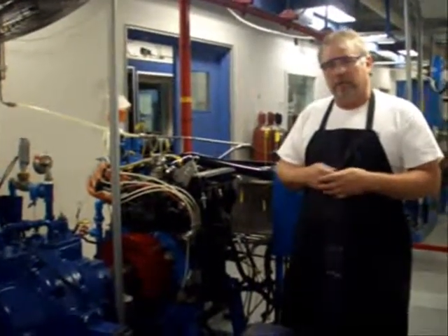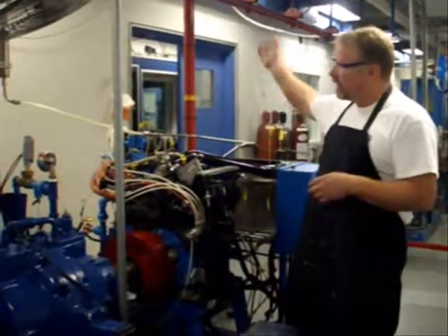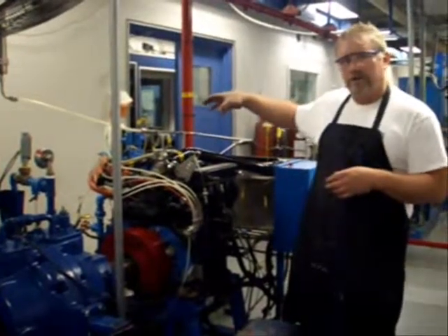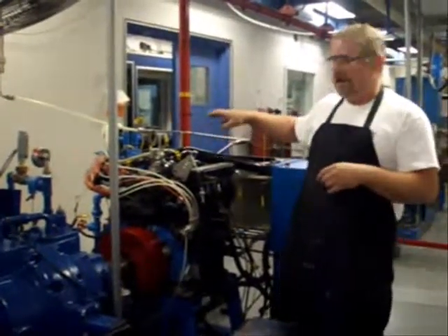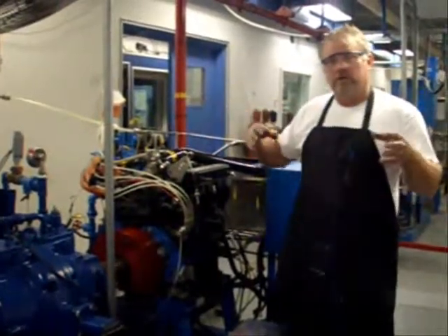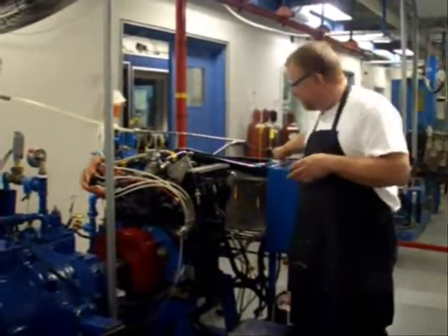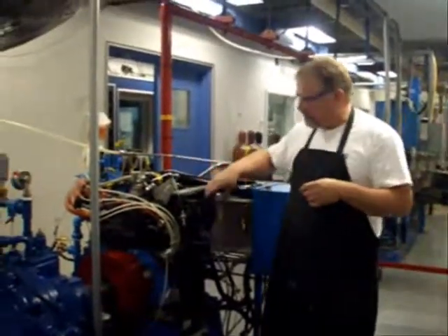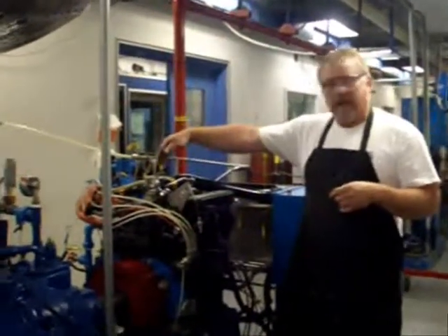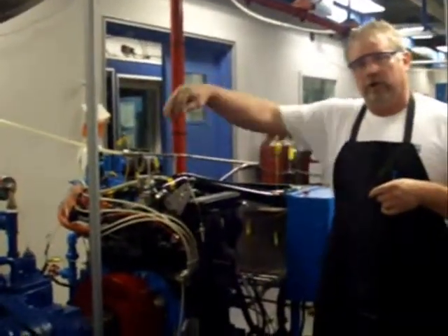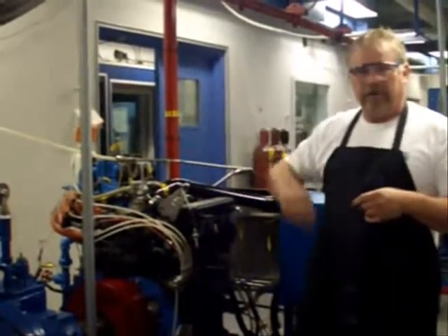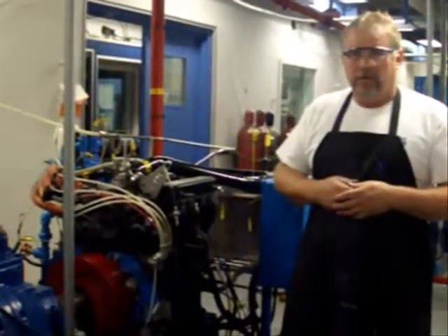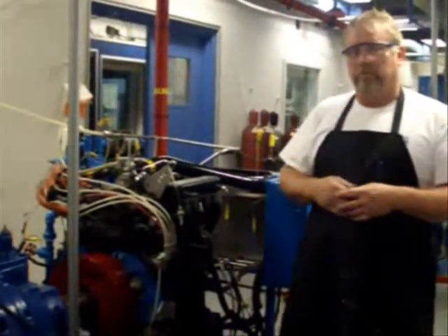We have 16 thermocouples on this engine. We're looking at the air as it goes through the engine. It comes into the air intake, goes through the turbocharger. I'll cover what a turbocharger is in a minute. But the air goes through the turbocharger, comes out, goes through an air-to-air heat exchanger called an intercooler. And then it goes into the engine, goes through the combustion process, and exits through the exhaust manifold, through the exhaust side of the turbo, and then out through the exhaust. So through that whole flow, we're looking at 8 different thermocouples reading the temperature as it goes through the process.